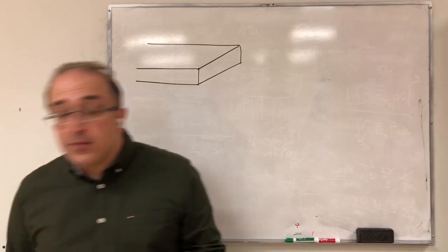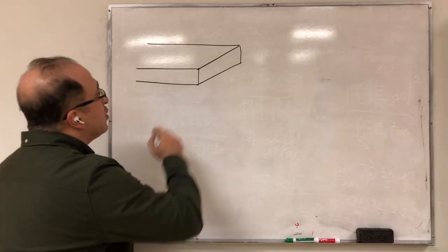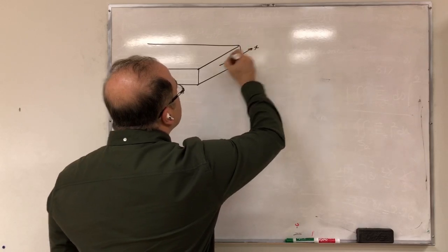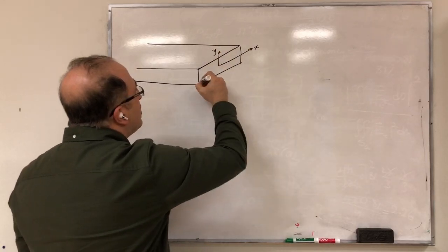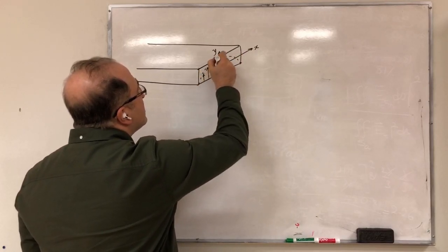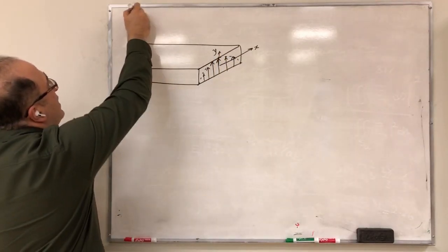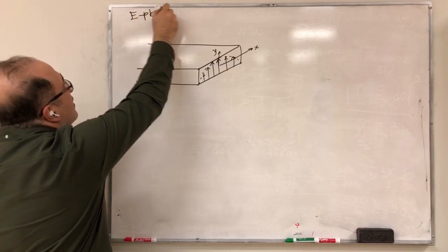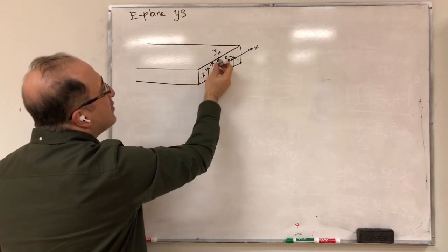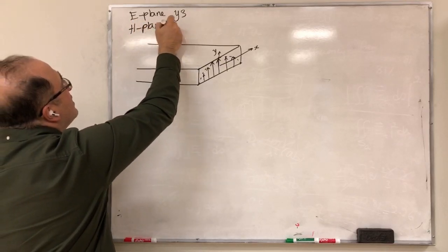One option is, for example, you consider your H plane. Let me also have some coordinate. It doesn't hurt to have some coordinate X and Y. And if you remember, this is the electric field distribution on the horn. Based on this, you know that your E plane is YZ. So Y is the direction of electric field, Z is the propagation, and then H plane is XZ.